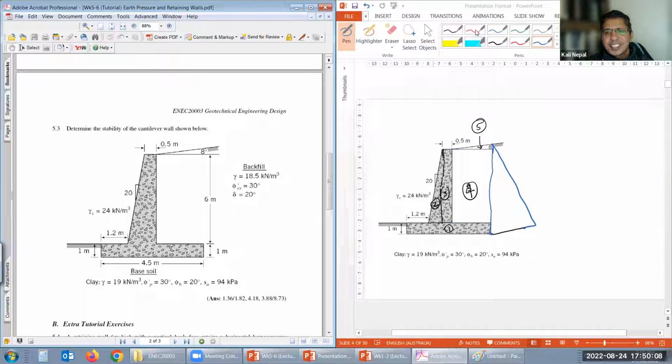Ka coefficient based on Coulomb's theory. Can you calculate Ka using the same equation? Don't waste time now calculating, you will calculate later. Can I use what I have here? Of course, you can calculate that, right? I have K as 0.33 here. All right. Oh, this is 30 degrees, yeah? 30 degrees is a lot easier. So the Ka value is 0.33.